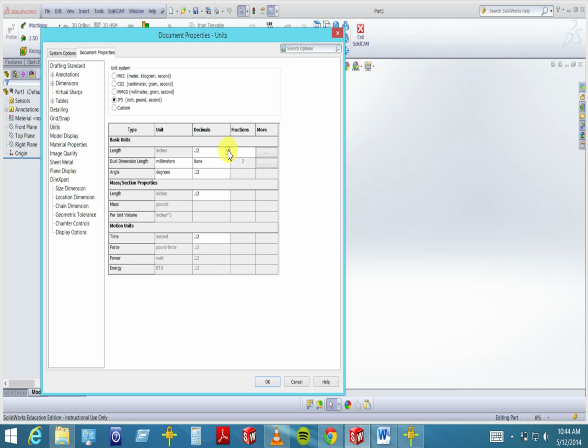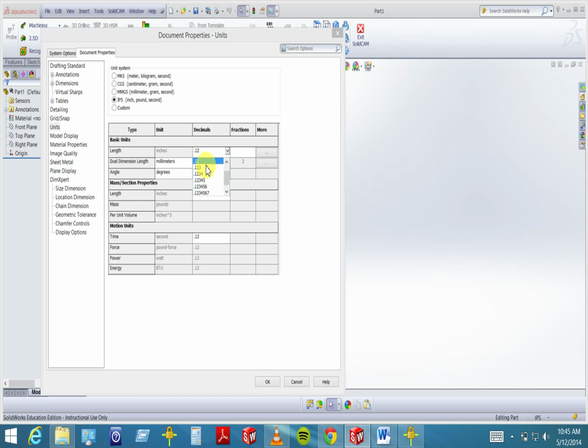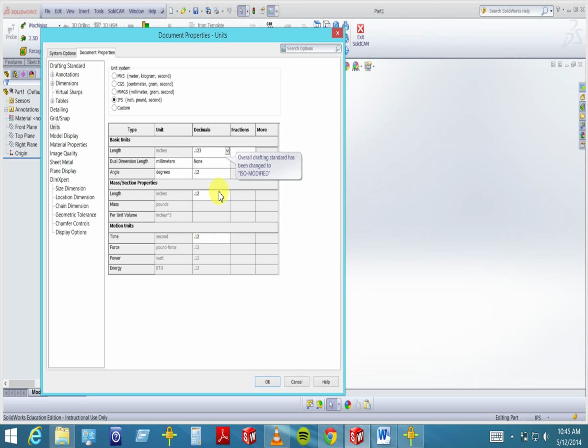most of the machines and the resolution of what we can do is easily in the 3rd decimal place in decimal equivalents, and sometimes even in the 4th decimal place. So I like to resolve my units to 3 decimal places most times. My angles I'm okay with 2 decimal places, but my lengths I like to be in 3 decimal places. So that's just one option I picked. Now there's a bazillion other options to pick in here. You can do whatever you want.